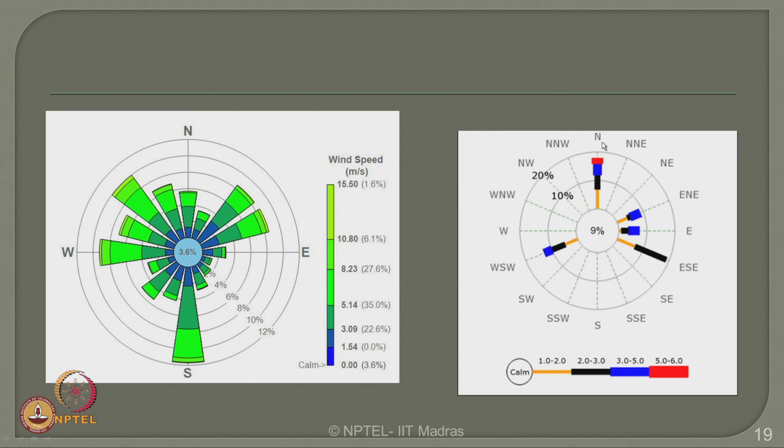So essentially a windrose diagram is a circular plot which has north, east, south and west divisions, and they can be further subdivided into categories as you see on the segment. Please understand, north is plotted at 0 or 360 and east is plotted at 90 degrees. Therefore, the plot proceeds clockwise: 0, 90, 180 at south, 270 at west, and 360 at north or 0 at north. It is one and the same here that north, east, south and west are plotted.